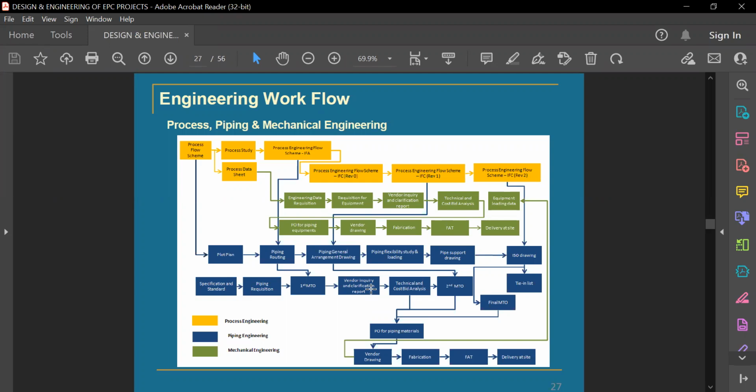So it is a good example, a pump. When it is procured, a mechanical rotating engineer will have to be involved, and then the electrical engineer also will have to see the data sheet. And then of course I have to see from the instrumentation point of view whether any vibration sensors or temperature sensors for bearings and all those things are being given by the vendor.